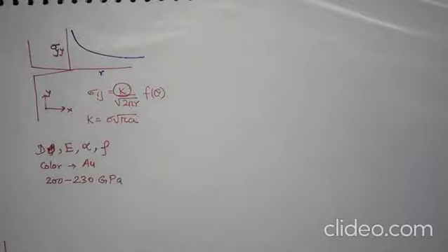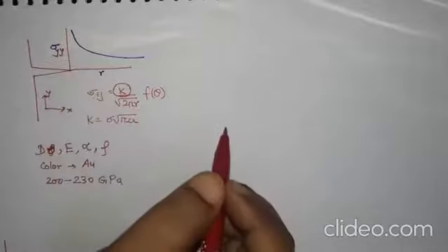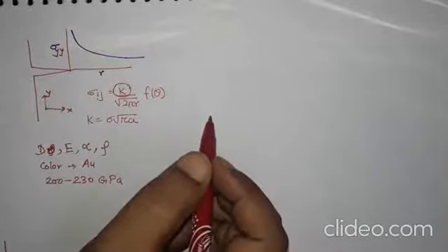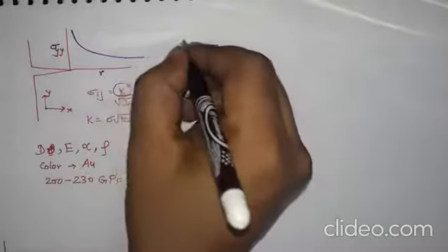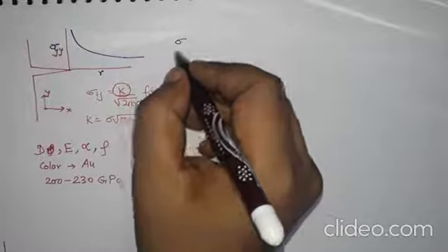And similarly, if stress intensity factor has a critical value, so what do you need? How do you know the fracture will happen? Like in Griffith's case, how did we know that fracture stress was a design parameter? That was an important parameter. We knew it because you will be increasing stress on the system, and after a certain value of stress, the material will not be able to take that load.